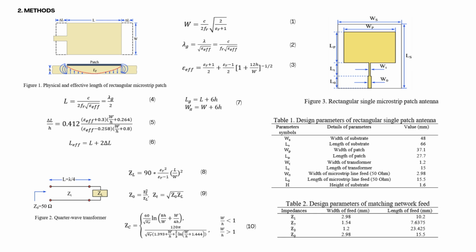and provided that the characteristic impedance Z0 is 50 ohms, we can say that there is a great impedance mismatch, and it can be checked by calculating the reflection coefficient. Ideal matching is characterized by a reflection coefficient close to zero. To minimize the reflection coefficient, we employ a matching technique such as a quarter wave transformer, which alters the impedance of the antenna to align with the characteristic impedance of the feeding transmission line. This approach adjusts the phase and magnitude of the reflected signal to diminish the reflection coefficient.